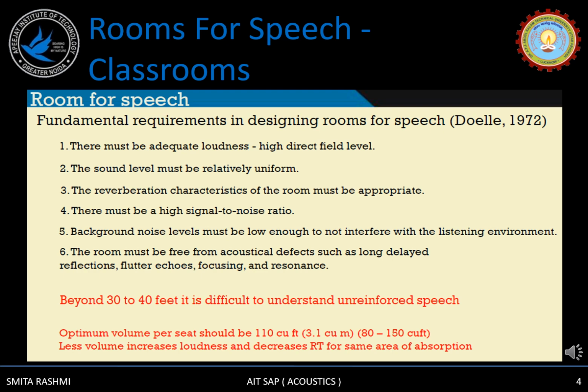Then the background noise level must be low enough so as to not interfere with the listening environment, and the room must be free from acoustical defects. We have talked about them: long delayed reflections, that is late reflections, flutter echoes, focusing and resonance. Due to resonance, standing modes develop, room modes develop. So we have to take care of all these kinds of acoustical defects that may occur in a room.